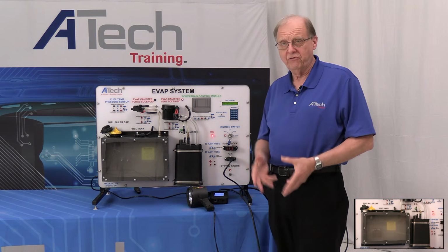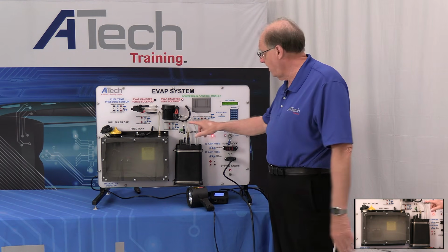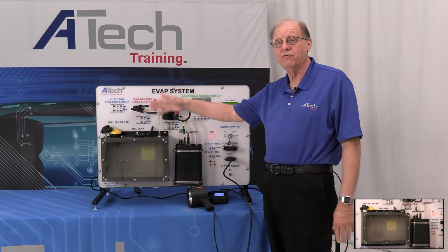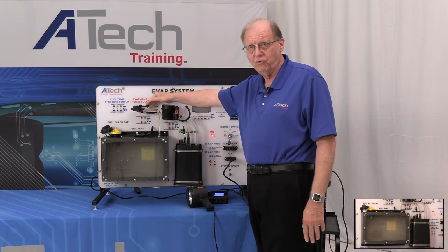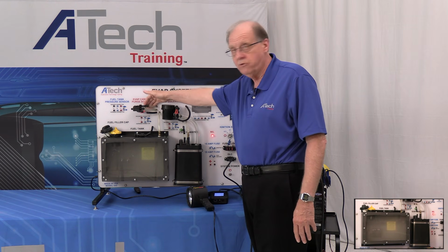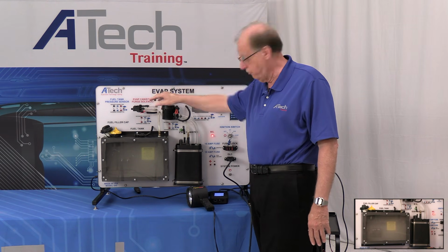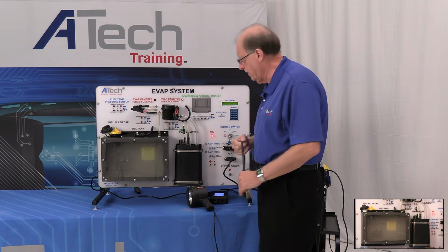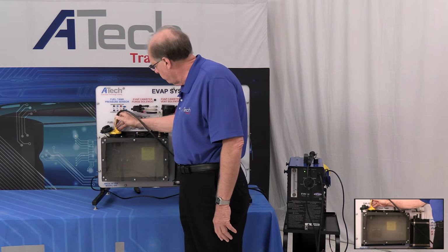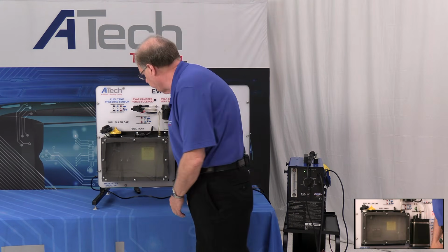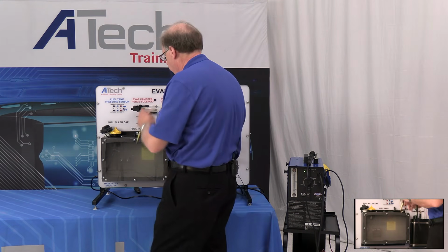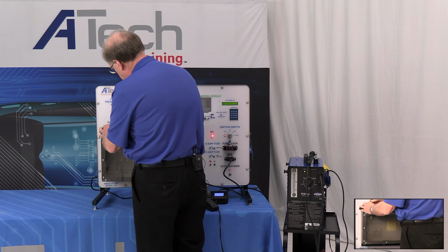Okay, I mentioned this earlier in the system. If you do not have the test port, you're going to have to go to the tank. There is another alternative that you can do. You can actually loosen a line going to the purge solenoid and put your smoke there. So what we're going to do is take this system and put our smoke here. We're going to be testing, well, we're going to try anyway. That'll happen to you guys every time, it always does.